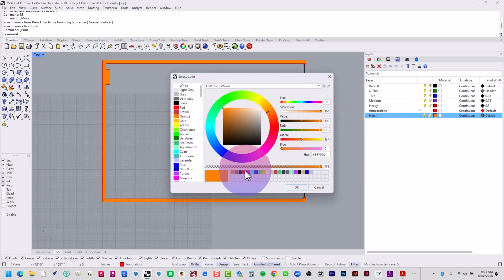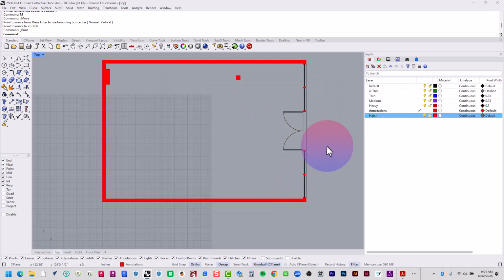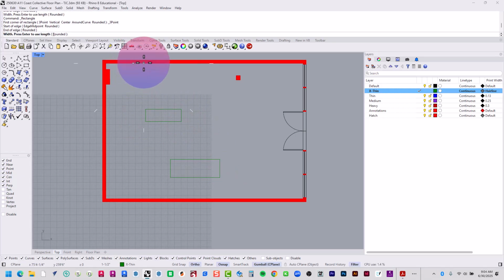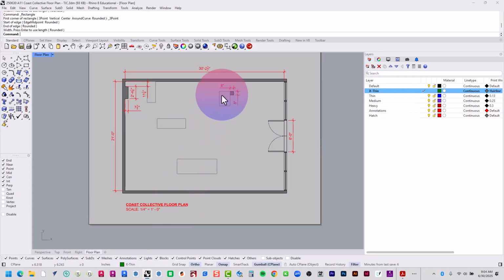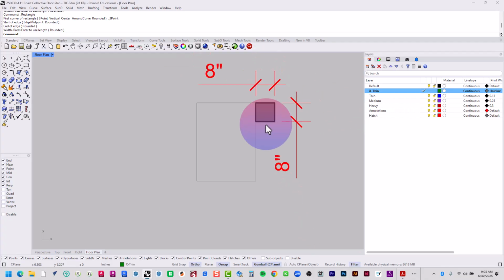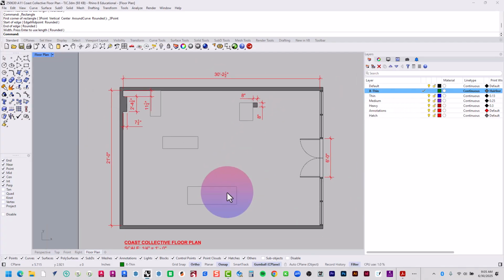All right, and then when I go here to floor plan, this is what they show up as. Sort of a nice thin line that's dark gray. So that way visually there's a hierarchy here. That's the goal when you're creating an architectural drawing, a hierarchy of line weights, and visually there's some sort of superiority, like this poche is the biggest, boldest thing that you see when you look at this floor plan versus these little furniture pieces. That tells you what's more important in this drawing. That is versus what that is, right? Especially in this room, all the furniture is pretty arbitrary architecturally.